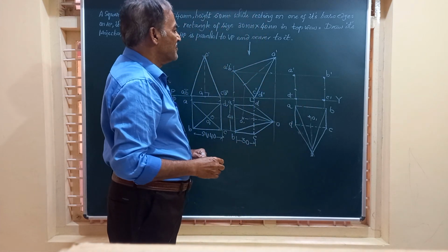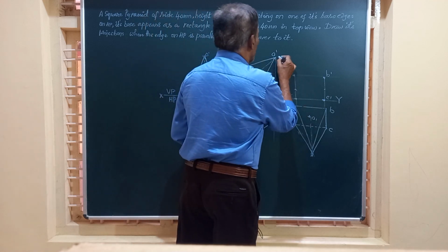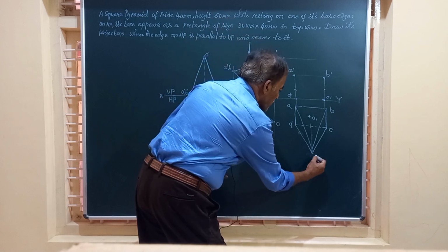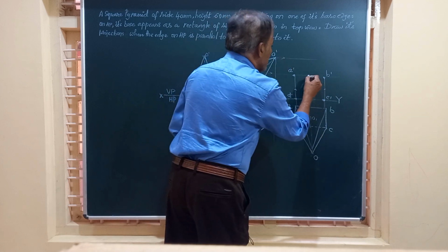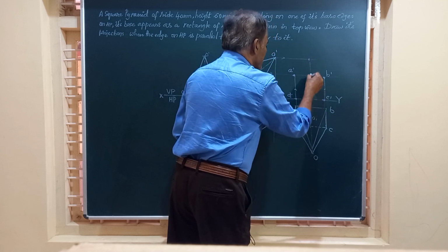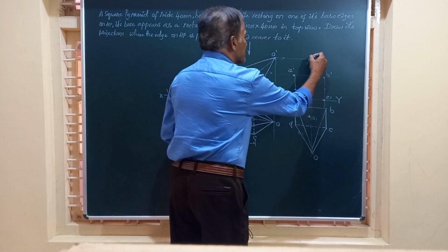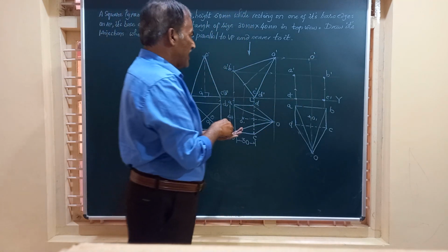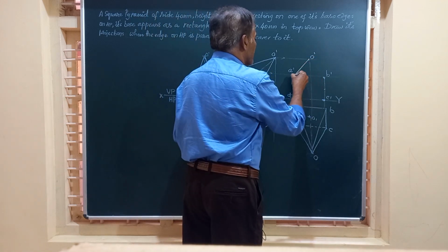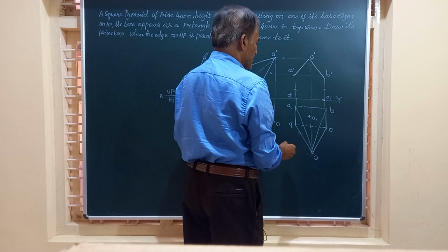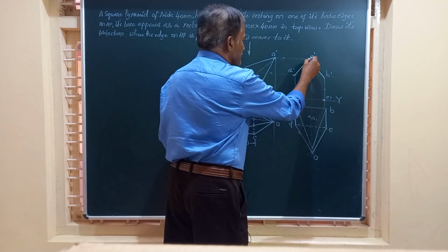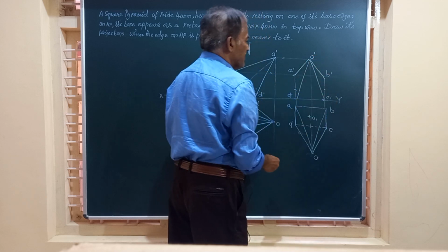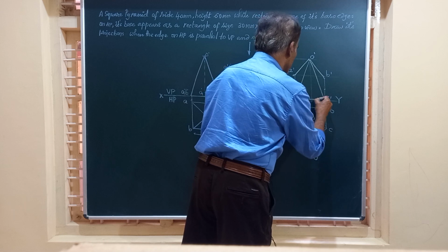Friends, you have got finally to obtain the point O, the vertex. Draw a horizontal line through O dash, a vertical line through O, that this line is going to meet exactly in the center. So I will simply show a line here. Friends, this is our O dash. Now we have to join all these by straight lines. So I have to join O dash to A dash, full line, O dash to B dash, full line, O dash to C dash is another line, O dash to D dash. Both OC and OD are visible. This is the last edge that is visible.